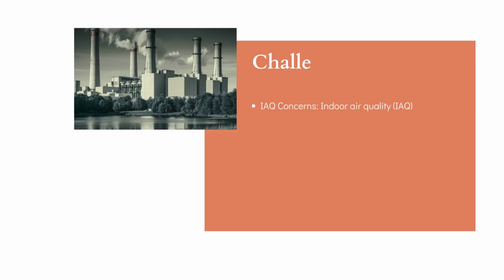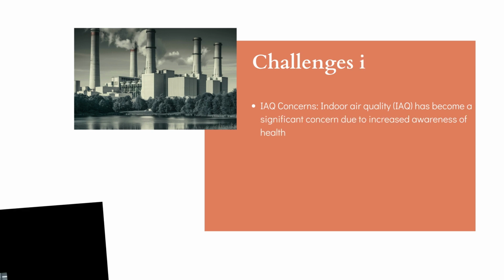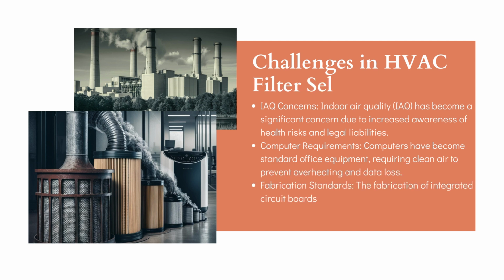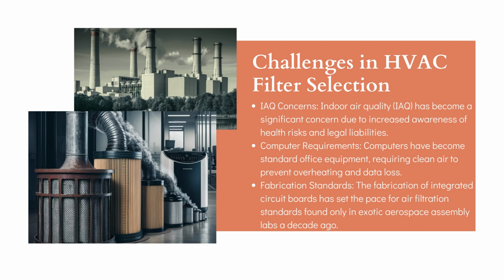Computers have become standard office equipment, and dust can cause overheating and failure in power supplies, as well as reading errors on hard drives and tape heads. The fabrication of integrated circuit boards has set the pace for air filtration standards found only in exotic aerospace assembly labs a decade ago. This has led to new challenges in HVAC filter selection.